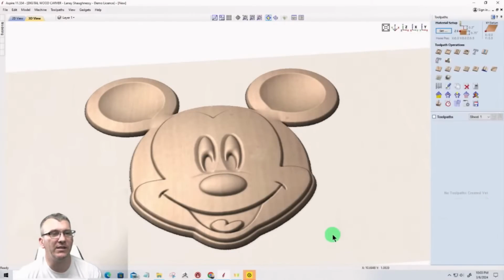Let me click cancel on this. So when I'm on the model here, if I move to the top of the nose, that's 0. As I come down, it shows me the depth. If I come to the bottom down here, that's my 0.6041, the model height. The very tip top is 0, the top of the board, because I'm zeroed out on the material surface.